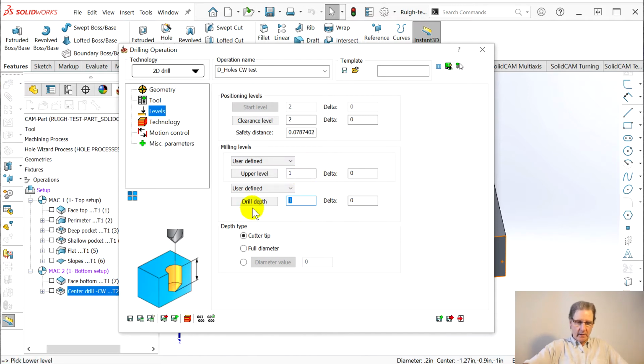That's incorrect. 0.0. I think this is savage that it just doesn't pick up the data from SolidWorks. 0.38 is the way the whole wizard in SolidWorks defines it. But when they do that kind of thing, they go to the tip of the drill, 0.38, not the way SolidWorks defines holes, which is the cylindrical part of the drill, the flank, the corner, however you want to call it, going down, 0.38. The actual depth of the tip of the drill with its 118 degree angle is 0.44.